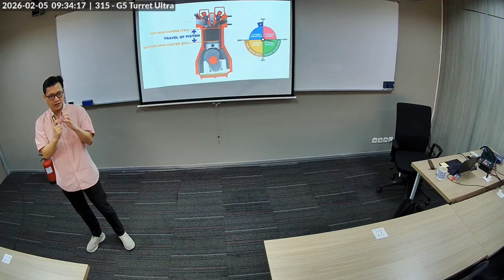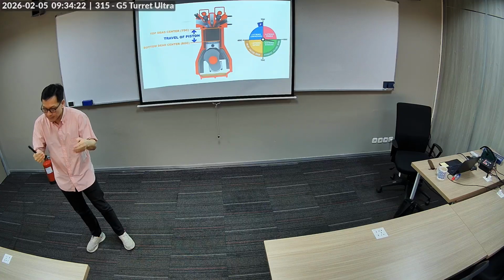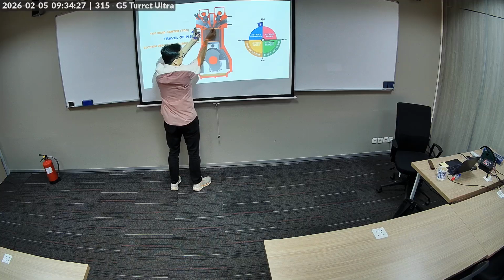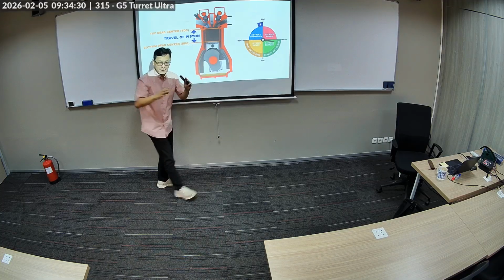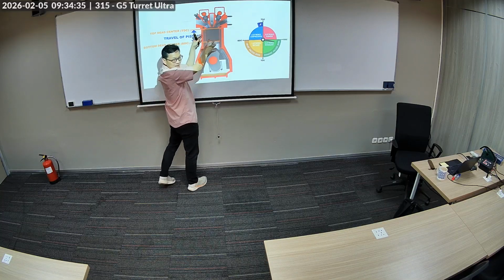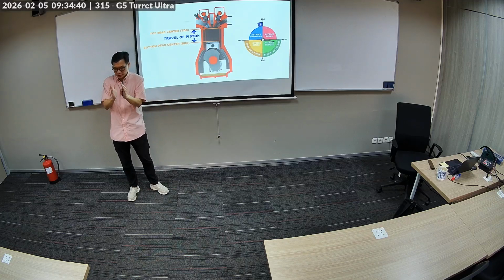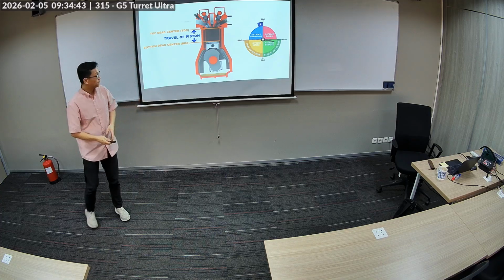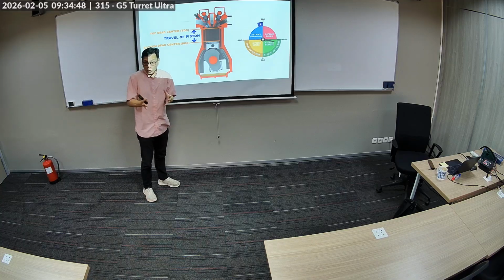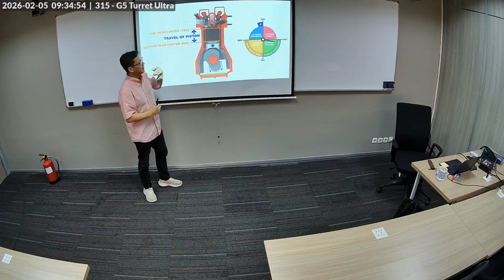the combustion chamber shape also determines the efficiency of your combustion, how good of a flame propagation you have, okay? Because the flame has to spread. Of course, this happens in milliseconds, but the flame actually takes some time to spread. And the shape of this guy, if it's too big or too long, is also not optimal. So depending on whether you want more low-end torque, high-end torque, or higher limits in the RPM, you design it differently.